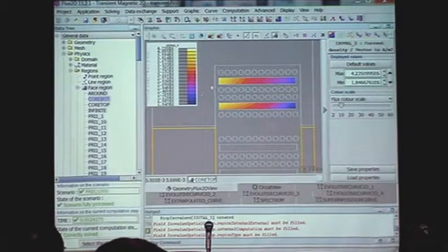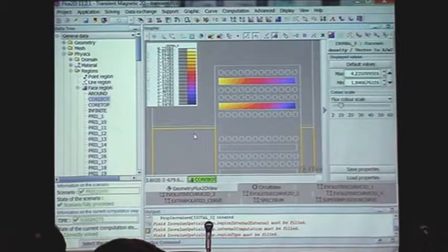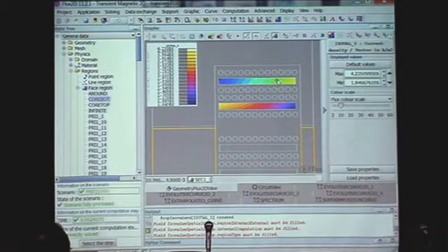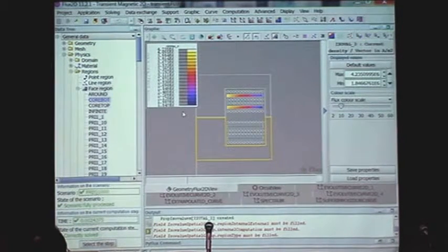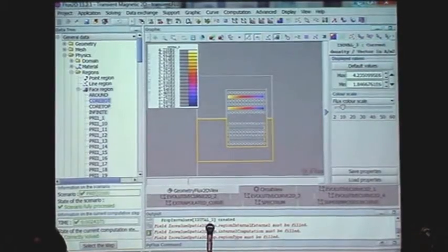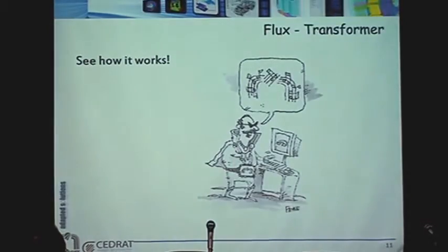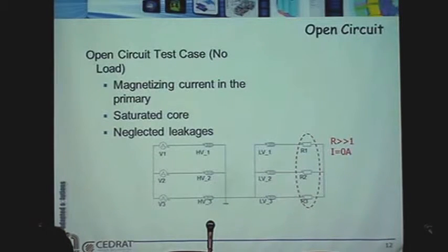We have a higher distribution on the inside because this is where we have the core. We probably have a slightly lower flux on the outside, not as much compression. This is why you have this distribution. So that's another type of transformer. It's not the one you find on the regular power distribution line, but nevertheless this is a type of tool that we can use. If we go to higher frequency, we can also go to copper trace. Very often those things are in 3D. This one was actually axisymmetric because it's only one single core, but you could imagine having a three-phase transformer in this way.